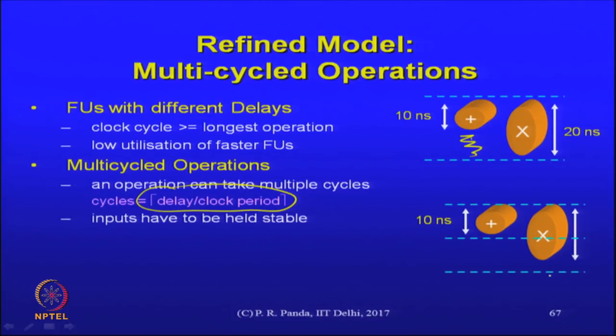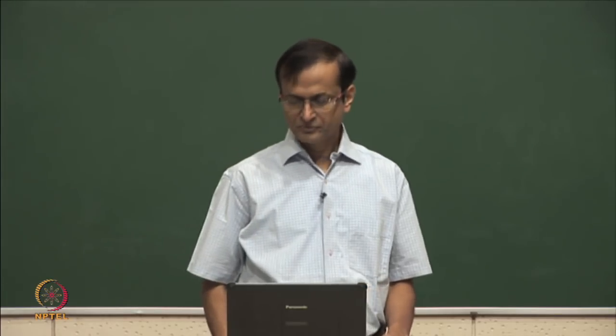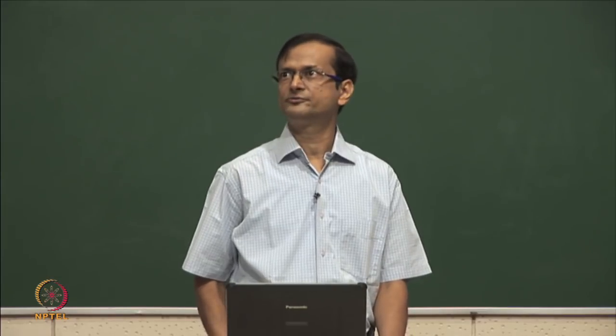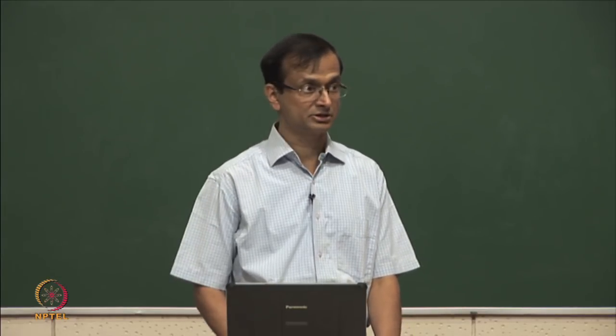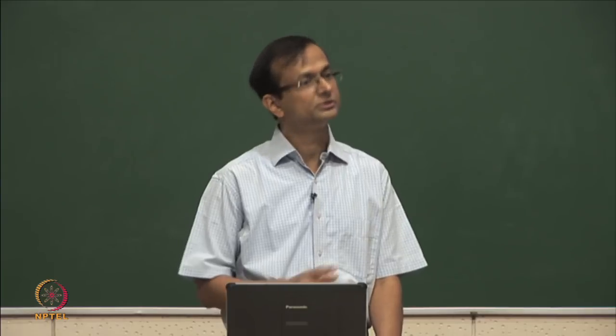The output of, in this example, the output of the adder has to be retained, like a no-op or a pipeline somewhere in between. It should be carried on to the next, some register inference or actually this pipeline has to. The output of the adder can be used in the second clock cycle, remember. If you wanted to, you could use it.